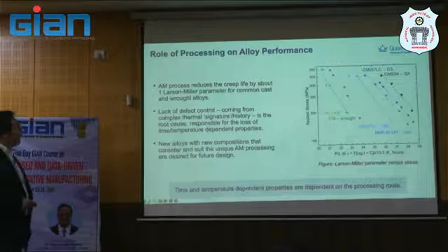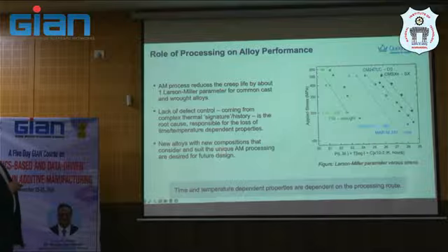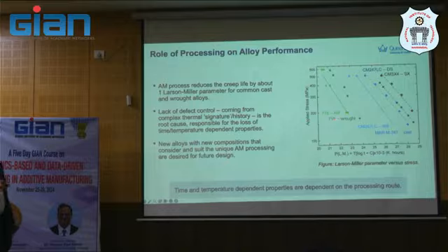Inspired by the performance of the alloy, you may see AM reduce the creep life, as shown in the Larson-Miller parameter plot. CM247, which is a single crystal superalloy, drops by one order of magnitude when you change to directional solidification, giving a lower creep life.